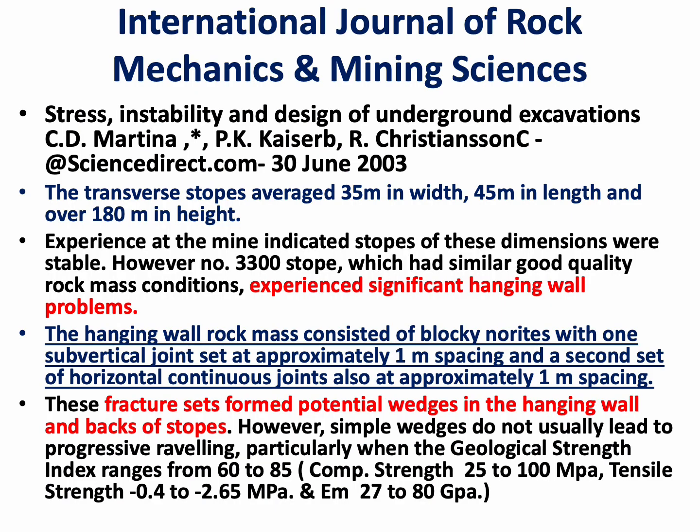The transverse stopes averaged 35 meters in width, 45 meters in length, and over 180 meters in height. Experience at the mine indicated stopes of these dimensions were stable. However, number 3300 stope, which had similar good quality rock mass conditions, experienced significant hanging wall problems.